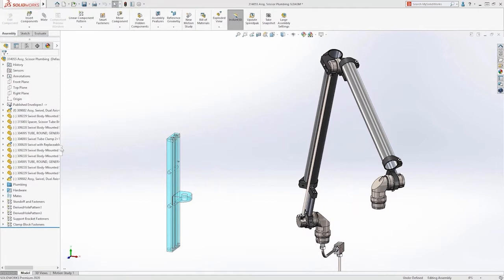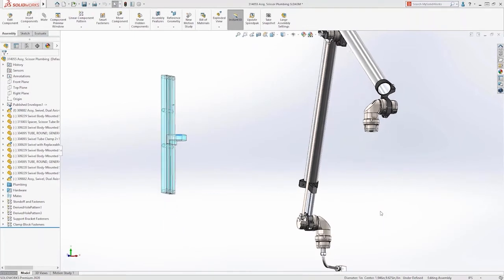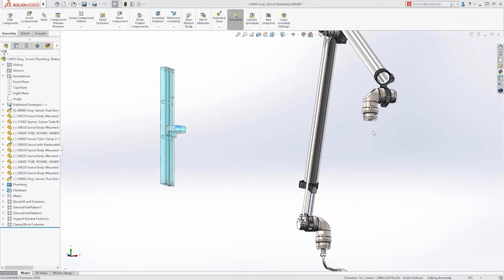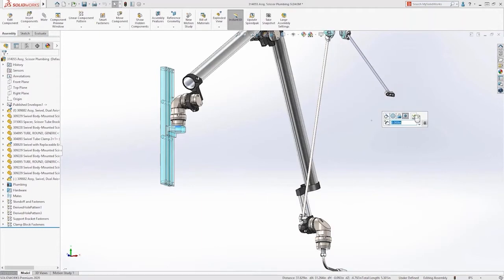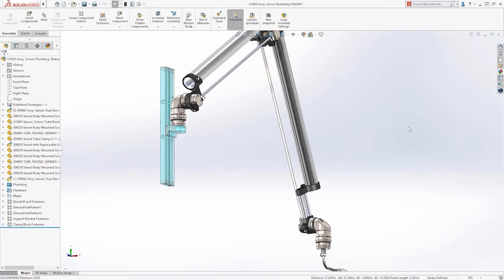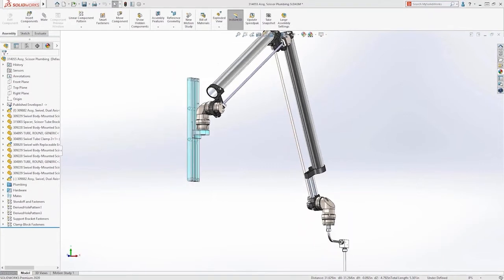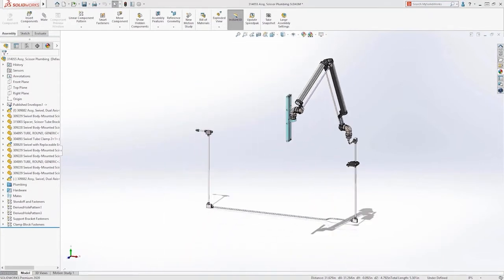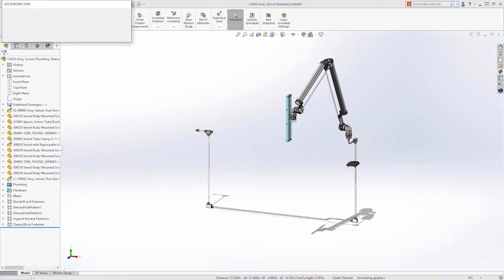As you can see, when we open up this subassembly, the envelope appears just as this shaded in region, but we're still able to select it and use it to create this reference for this mate here. This is great because this means that that mate has an external reference to the model, which is being created, but we haven't had to, again, work in that top level or copy data over from another subassembly in a different way.